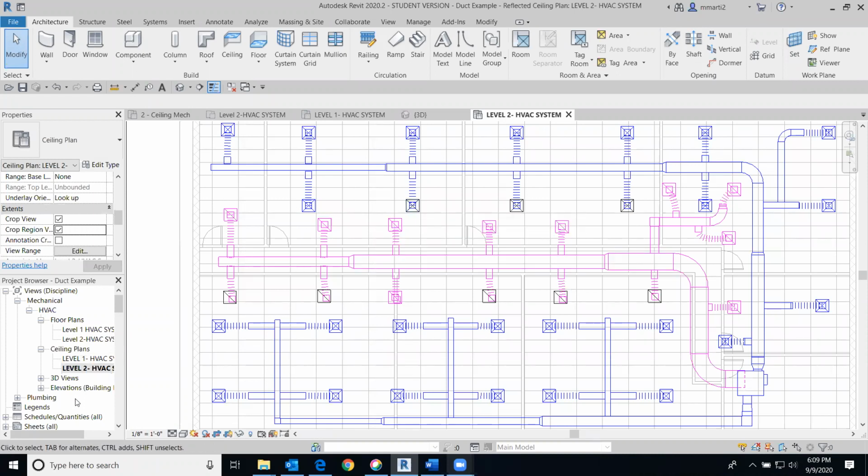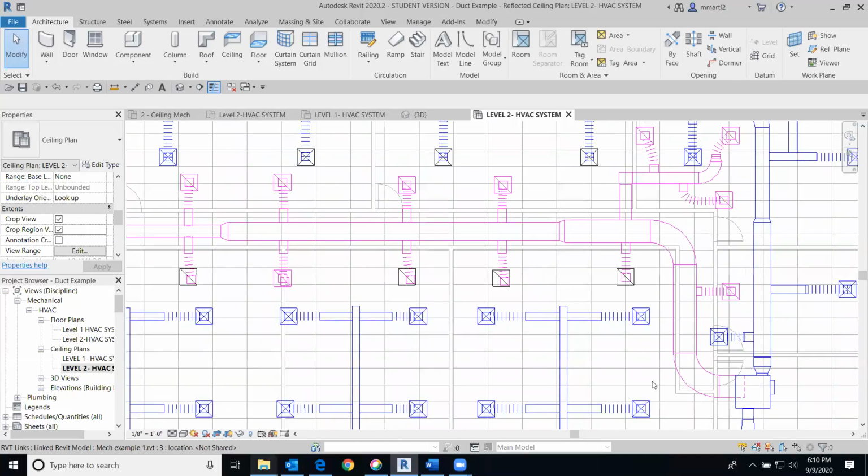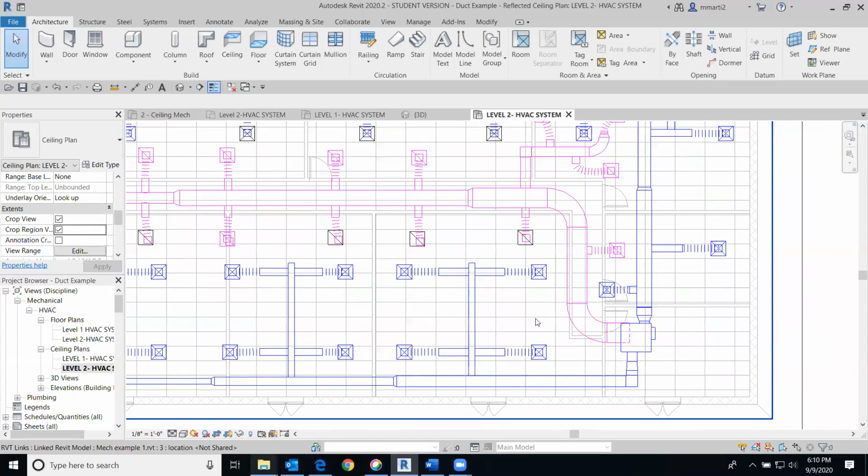Now remember, when we created this view before, there's that plenum, that space that goes beneath the floating ceiling, which is set at 8 feet, and the actual ceiling, which is at 10 feet. So that's the space that you're using to create that ductwork in. That's why it may look a little confusing, but in this view, since it is a ceiling view, which is where we're laying out this ductwork, you want to see where the floor is, where the walls are underneath on that first floor. Make sense? Okay. Yeah, any other questions like that, just yell out.